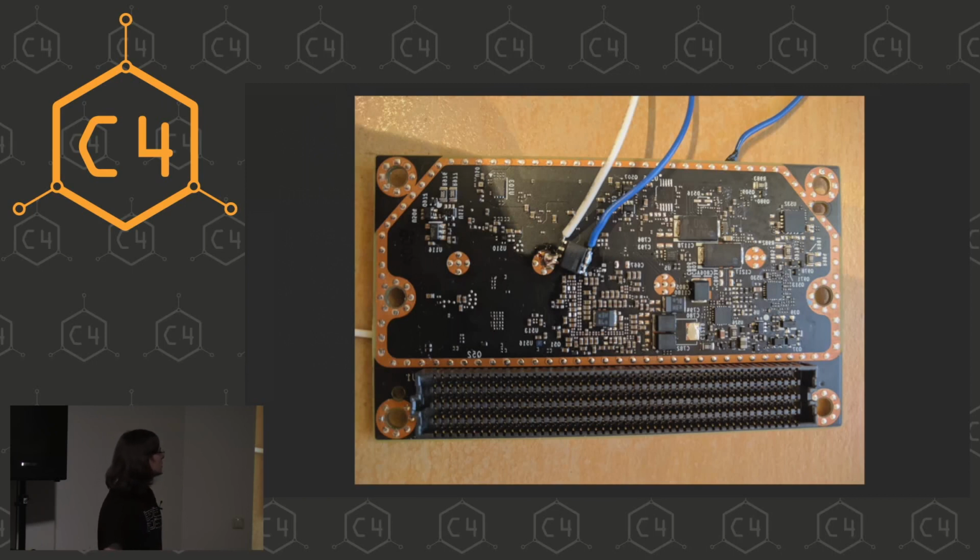This is where I hooked up my oscilloscope probe, the blue wire, and the white wire is the signal line that my ChipWhisperer, something that you can use to glitch chips, puts the signal on to turn on this MOSFET and pull this voltage line to ground to this pad.